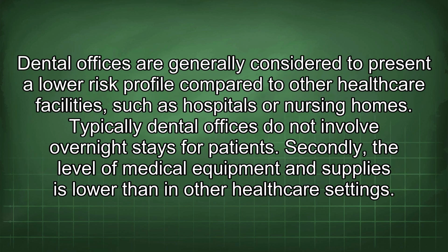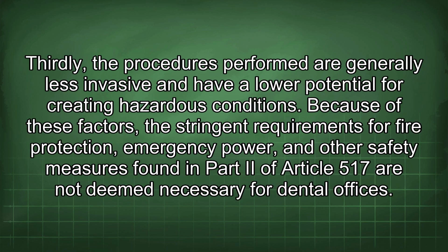Dental offices are generally considered to present a lower risk profile compared to other healthcare facilities such as hospitals or nursing homes. Typically, dental offices do not involve overnight stays for patients. Secondly, the level of medical equipment and supplies is lower than in other healthcare settings. Thirdly, the procedures performed are generally less invasive and have a lower potential for creating hazardous conditions. Because of these factors, the stringent requirements for fire protection, emergency power, and other safety measures found in Part II of Article 517 are not deemed necessary for dental offices.